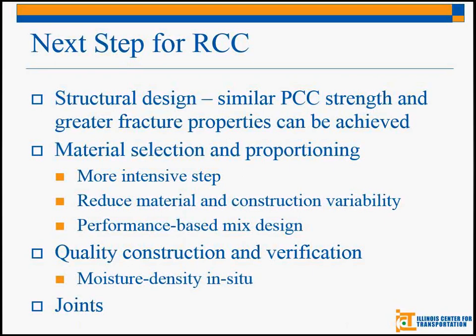Creating the actual mix design can present a problem, as seen with the recycled concrete aggregate due to its high absorption capacity. And one interesting thing is with joints. As I mentioned earlier, you don't typically have joints with RCC, but if we can introduce joints into it, then that might also help bring it to be even more relevant in terms of concrete pavement.